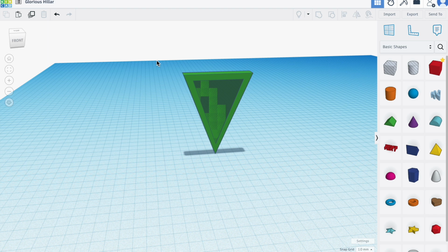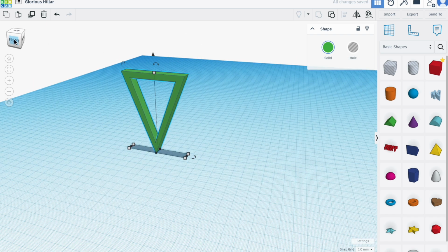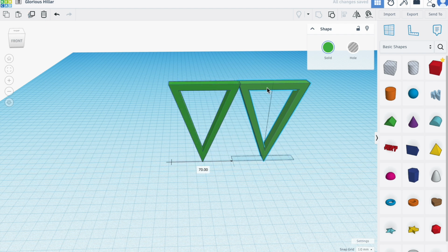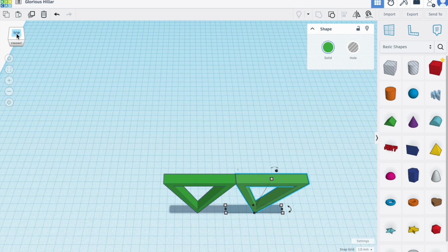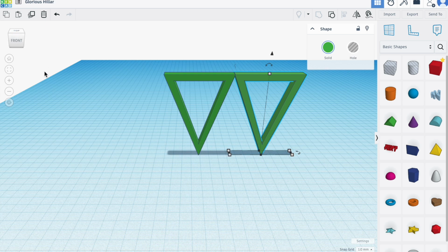Now when you select both objects, drag your mouse over both and you say group. It puts a hole into your triangle. Now, you don't have to do this over and over again. You can simply copy and duplicate. So hold Shift to move it over. By holding Shift, it makes it so that the triangle doesn't jump all over your grid and it stays in a horizontal line. See how it's stayed in that same visual plane? Okay, and now we'll repeat.